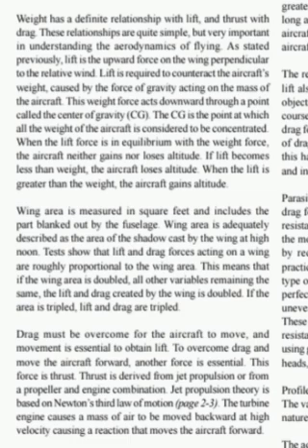When the lift is greater than the weight, the aircraft gains altitude. Wing area is measured in square feet and includes the part blanked out by the fuselage. Wing area is adequately described as the area of the shadow cast by the wing at high noon. Tests show that lift and drag forces acting on a wing are roughly proportional to the wing area. This means that if the wing area is doubled, all other variables remaining the same, the lift and drag created by the wing is doubled.